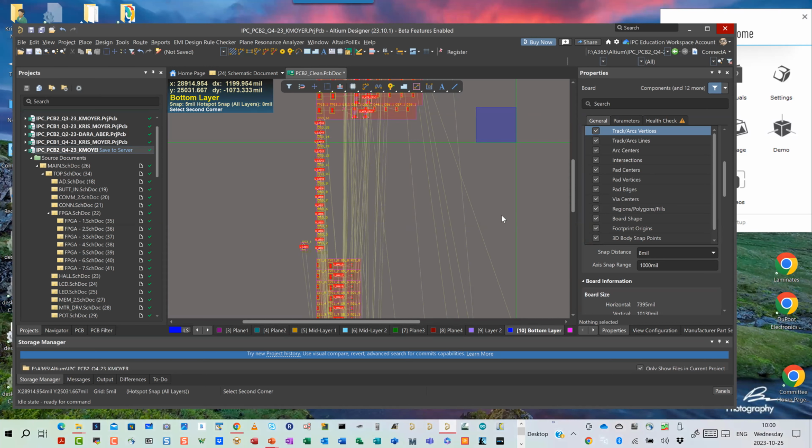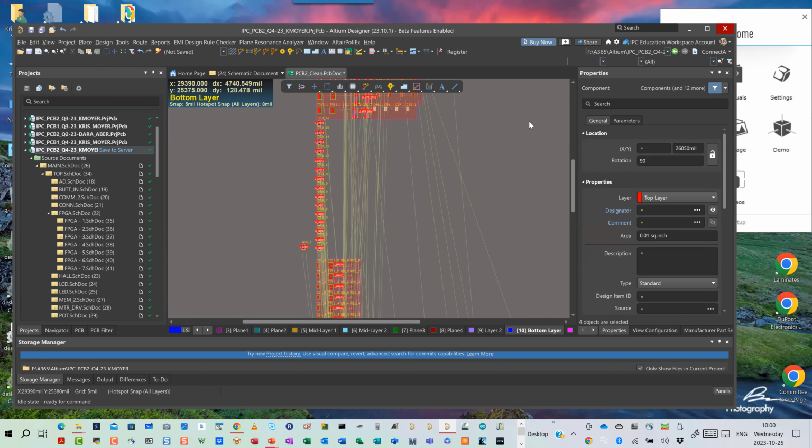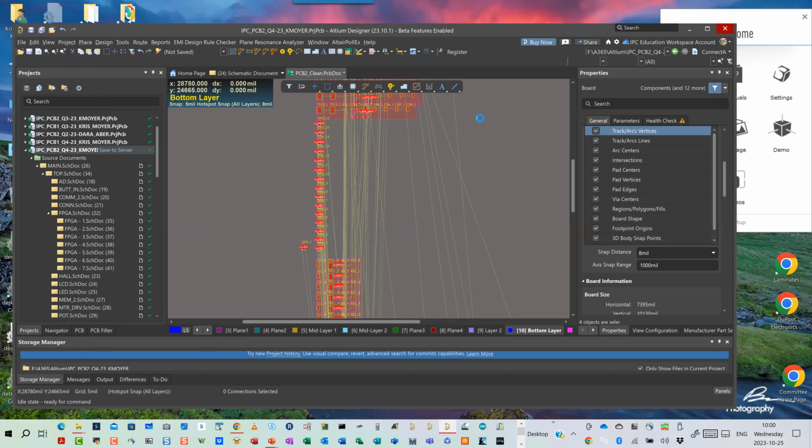We're going to go about 5 minutes past this. I'm going to show you one last feature here and then turn you loose to keep working on the other circuits. So again, from over here, if I have a box right here, if I go to the right, it's blue. If I go to the left, it's green. A blue box means the feature I wish to select must be fully enclosed within the box. A green box means the feature only needs to be touching the box.